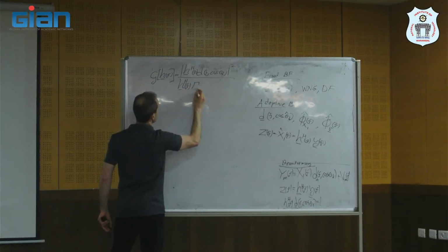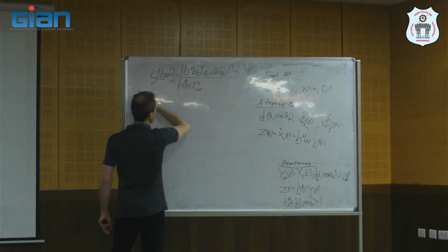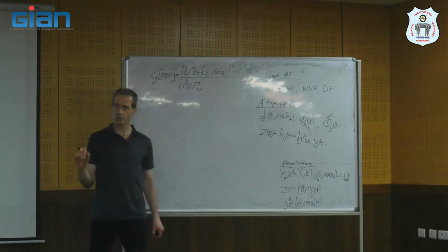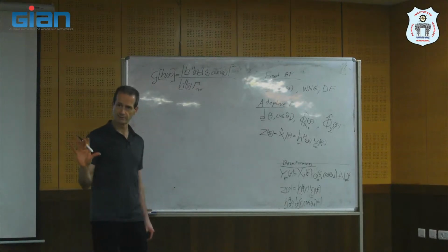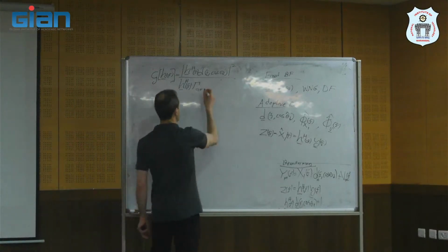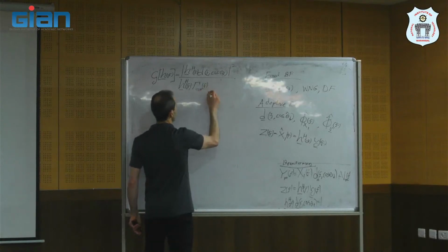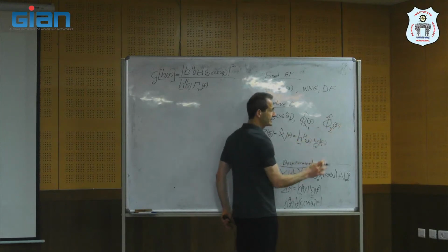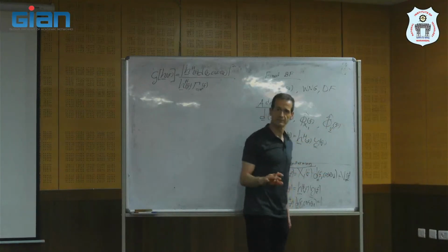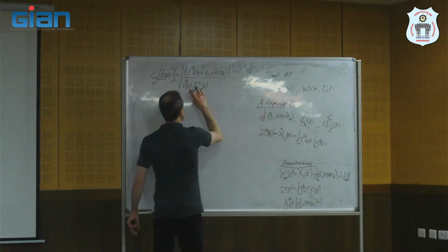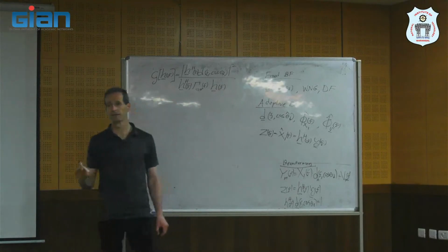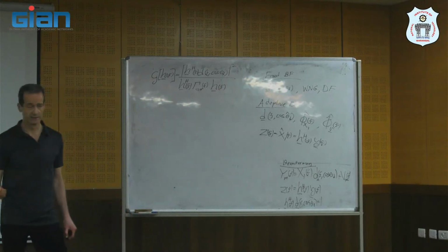We call it gamma 0 pi in the slides, but actually this is the normalized correlation matrix of diffuse noise for the frequency f. So this is actually gamma v divided by gamma v1. This is the normalized correlation matrix. This is the array gain for diffuse noise.